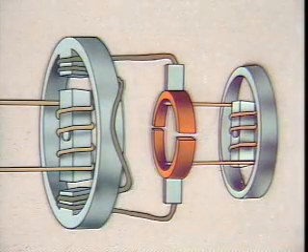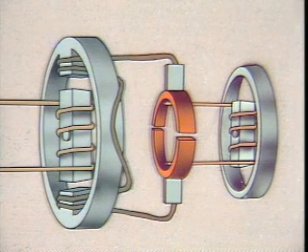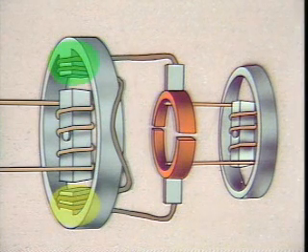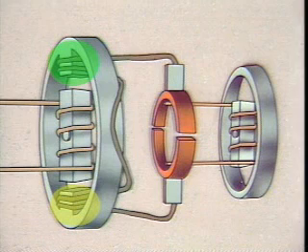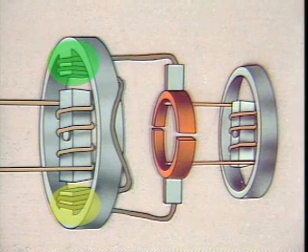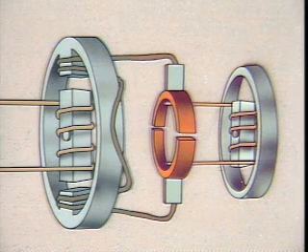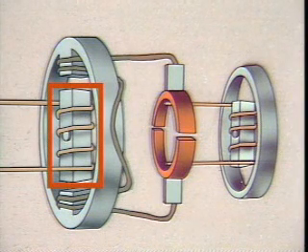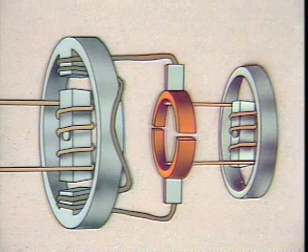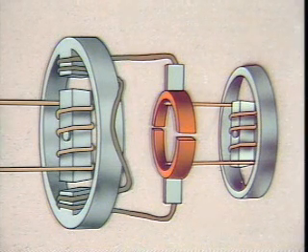The exciter is different from the generator because the magnetic field is created in the stator windings of the exciter, rather than in the rotor. Another difference between the exciter and the generator is that in the exciter, voltage is induced in the rotor windings as they cut across the magnetic fields around the stator. Like the generator, the exciter uses an electromagnet for the magnetic field.